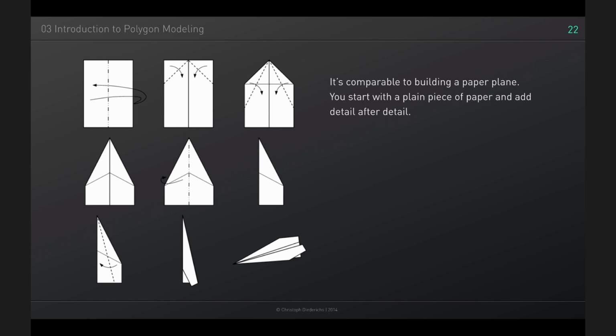You start off with a very basic object like a cube or a sphere, a parametric object for example, or you can use your own NURBS generated object by using the splines. And you make it editable to access the polygons, and then you use a variety of tools to add details to your object. And then in the end you hope it looks good.